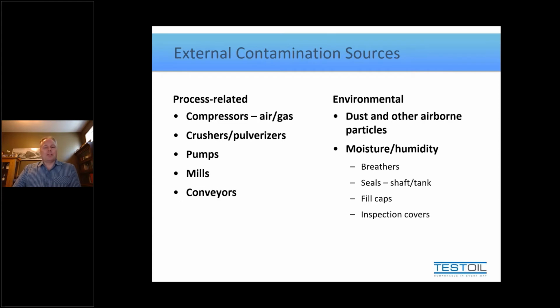When we start thinking about other sources, though, we start discussing ones that are related to being on the outside of the machine at first and then working their way to the inside, so what we call ingressing into the machine. And many of those have something to do with the environment near where the machine is operating, and some of those may be process related. So if we're crushing, grinding, milling anything as part of what we do with that machine, then we're creating particulate outside that machine, and some of that may end up being drawn to the inside.